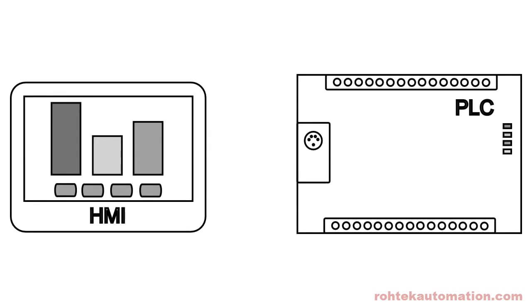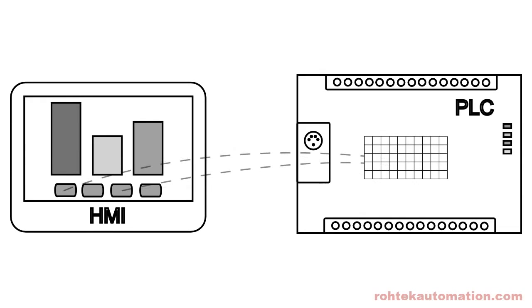Next up is reliability. The main point here involves keeping the PLC, which is engineered to be extremely reliable, in control wherever possible. You may be able to directly control a PLC's outputs with an HMI, but having the HMI instead write to the interface table allows the PLC program to maintain a degree of control.